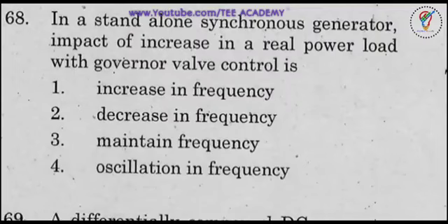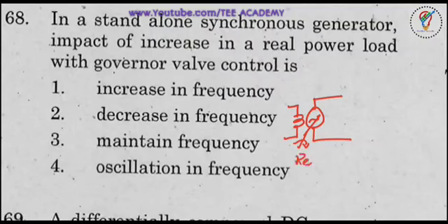In a stand-alone synchronous generator, so only one alternator is working. Impact of increase in real power. So if you are increasing real power, it means you need to increase the mechanical power, right? Not excitation. Excitation will be kept constant. Now if you increase the real power, load with governor valve control. So here we have governor valve control.